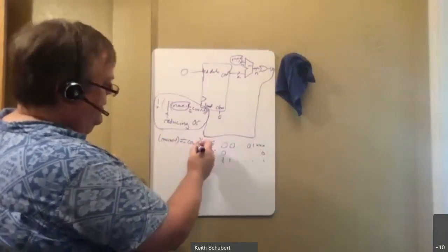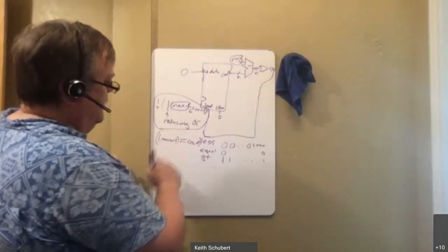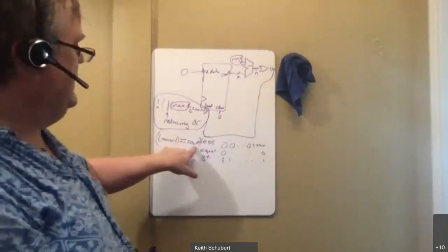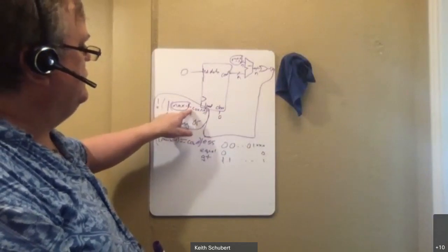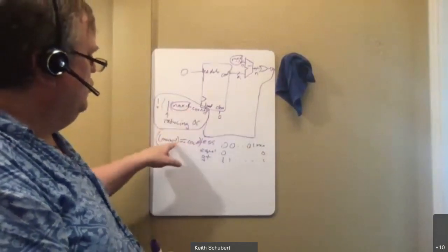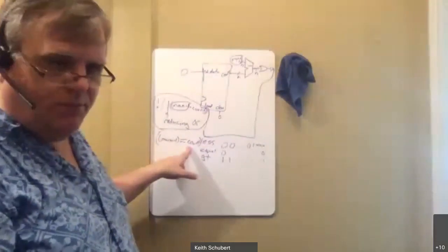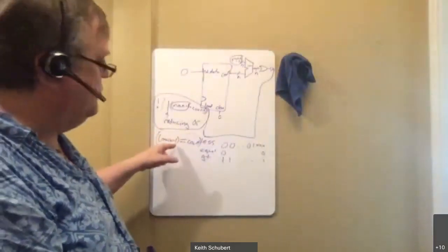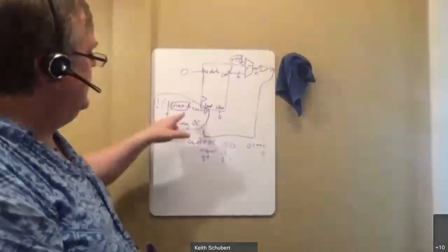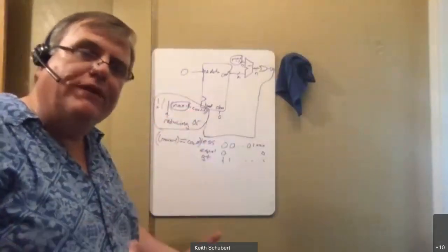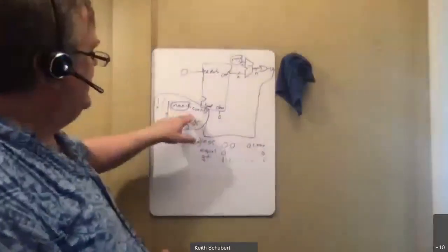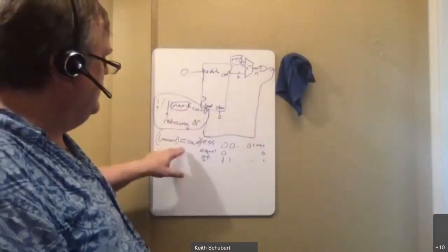That's a comparator right there. Okay, so that's easier to write. The only advantage that this one gets is that you may or may not have a comparator circuit built into your system, so you might have to build this, and that could be more complicated. Whereas the adder subtractor might be built in, so you have very fast hardware to do it. So that's the only reason I would do this instead of this.